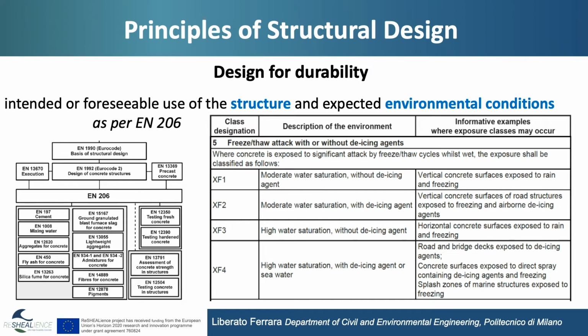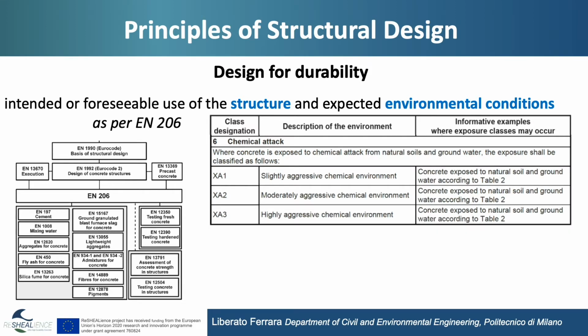And finally, we have the chemical attack class, distinguished into 3 subclasses, XA1, 2, and 3, generally related as slightly aggressive, moderately aggressive, and highly aggressive.